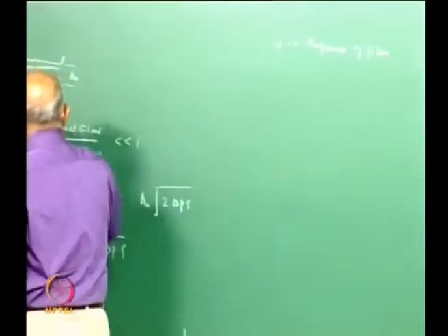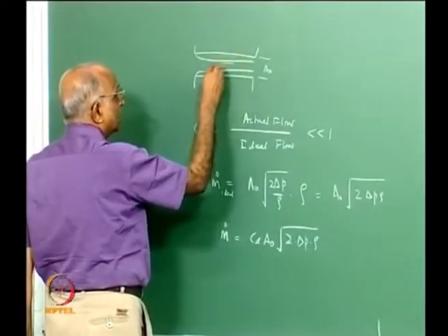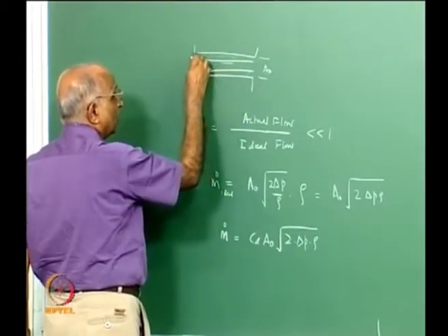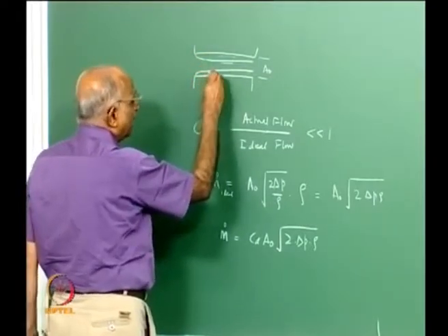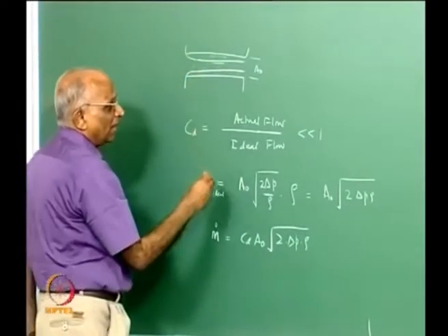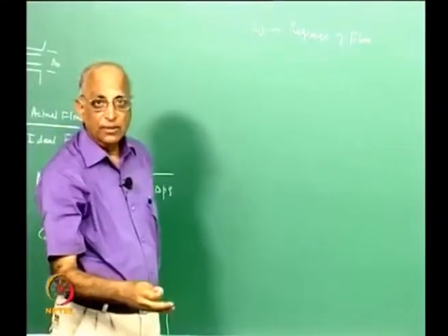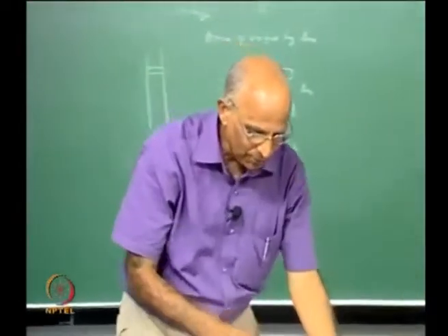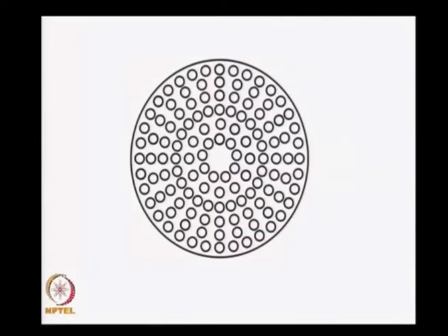The flow sometimes runs full, such as it happens when the orifice is large, sometimes with cavitation it gets separated, or when the orifice is very small, due to the vena contracta it gets separated, and therefore for the different conditions we would like to examine the value of CD, which I do subsequently. I thought we should not spend too much time on it, because we are shifting the topic from liquid propellant rockets to one particular element of it.